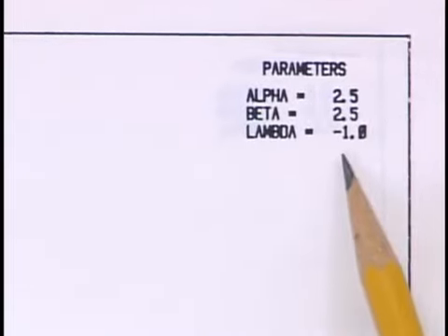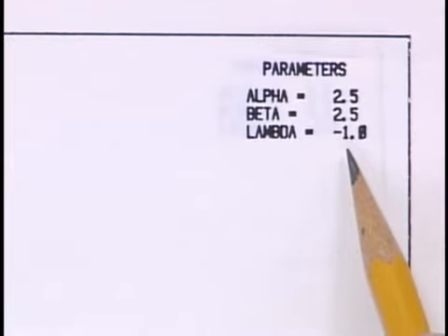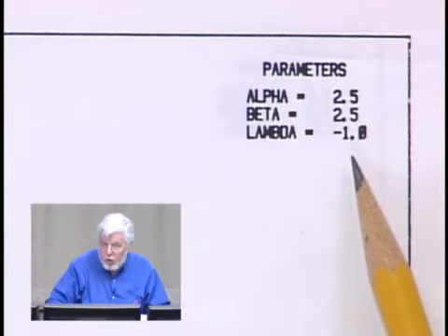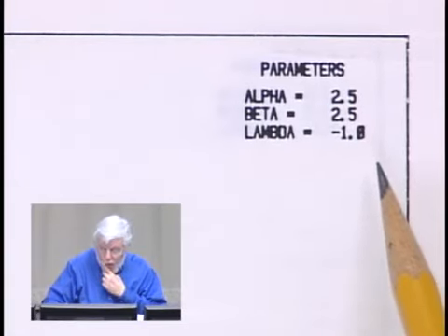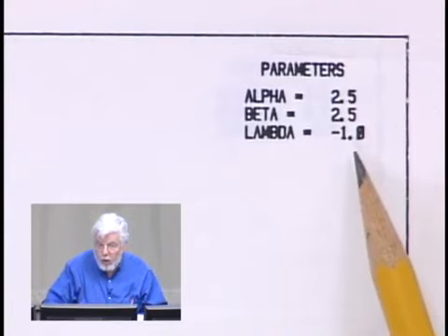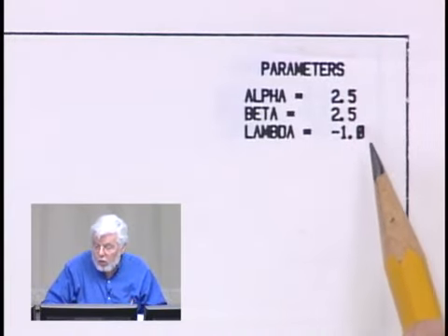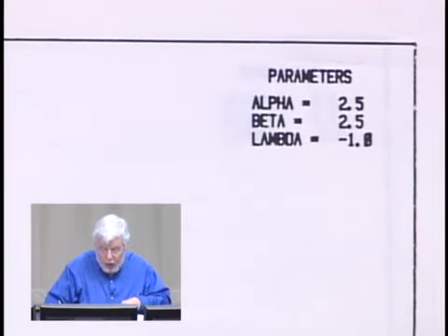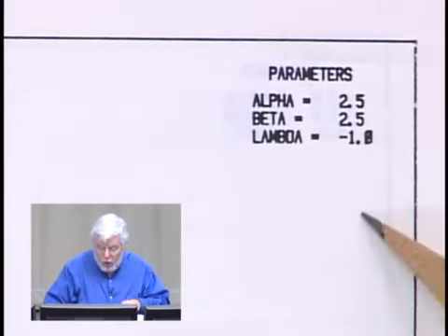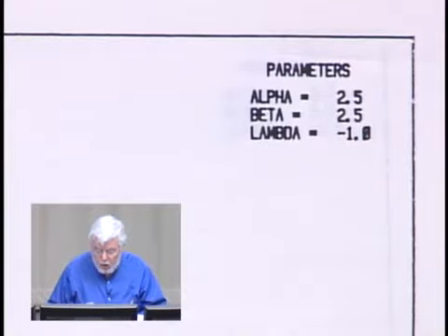A negative gear ratio indicates that you have a pair of gears, typically, one of which turns the other in the opposite direction. If this were positive 1, it would imply that you had an idler gear present to reverse the rotation so that crank 5 would turn in the same direction as crank 1. So this ratio can be either plus or minus, and it can be either an integer or not, though I think integer is a more practical solution. A negative 1 gear ratio doesn't give interesting curves.